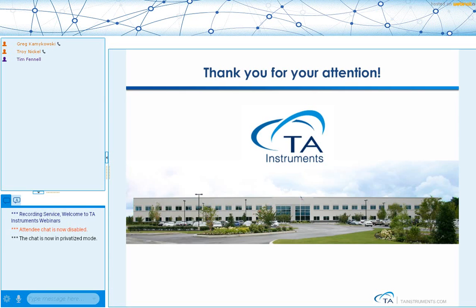And what I would say is that when they do rheological testing like this, they should get an excellent correlation between a crossover point like this, if they get one, and what they might be calling a gel point in a practical sense. So they might be doing it phenomenologically by just doing a tapping test and see what kind of response they get. But I would say our measurement is more accurate and precise, but it would correlate well with the practical test that someone might be doing right now.